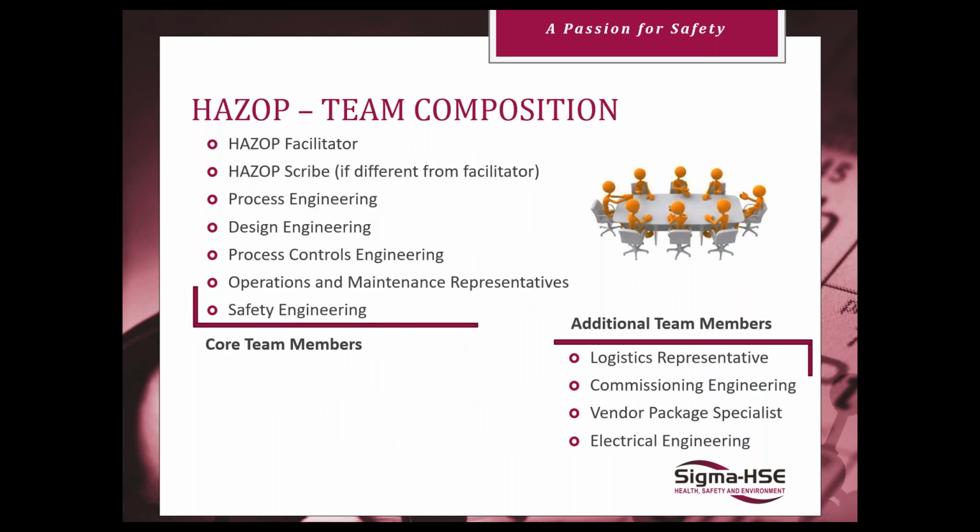Okay? All right. So team composition of your HAZOP. Team composition is really important. You want to make sure you have the knowledge in the room that's going to make your study successful. Always need a facilitator trained and experienced in the method being used. If it's a large enough study, you've got a large thing you're going through, usually you'll have a scribe as well. So you have the facilitator leading and directing the discussion, and the scribe will be recording within the software. If it's a smaller, less complex process, a lot of times the facilitator will scribe as well.